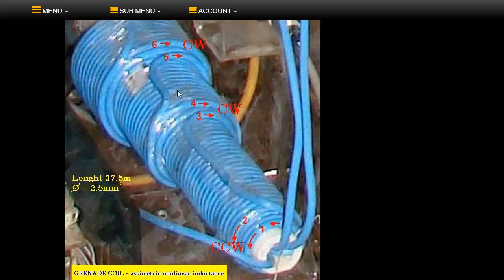So this buck boost transformer here, if it was resonant, then at a resonant point, the amplitude of the voltage would be at its highest. But because we've only got effectively half a length of wire here, that's different. Remember we've got 2 turns to 1.5 turns, so we've only got part of this that's inductive. So the problem again, as we've seen before, is getting the voltage up, because we have a cancellation, and the voltage is going to drop.